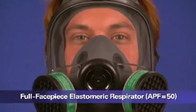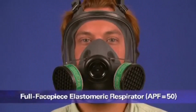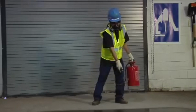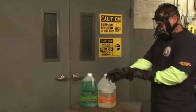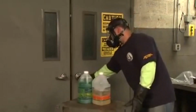This is a full face piece elastomeric respirator. This type of respirator provides a higher level of protection than a half face piece respirator because it has better sealing characteristics. Since it covers the user's eyes and face, it can also be used to protect against liquid splashes and irritating vapors. Like the half-mask elastomeric respirator, this respirator is a tight-fitting, air-purifying respirator with replaceable filters or cartridges attached to a rubber or silicone facepiece. It needs to be fit-tested.